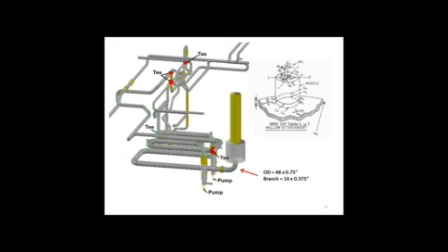This is a rotating equipment model, so the cycles and the stresses aren't so important here. When you see these, the first thing I always do is identify where the pumps are, and then I find where the T's are. And I say, are the T's close to the pump? So in this system, I see that there's a T that looks like it's close. There's a big head that's not in Appendix D, so I'd need to run another tool in FEA tools to evaluate that elliptical head. And then there's other T's that are removed from the system, but there's a good chance that those aren't going to affect things very much.